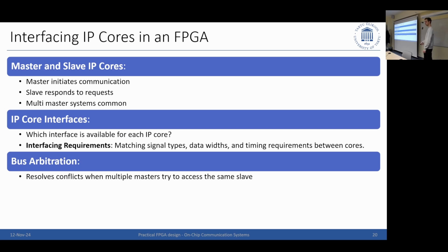Maybe you decide because of this that you want to use AMBA 2 or AMBA 3 on the overall system, so use AHB. And of course that's a valid option. But you also see that I can do everything else with AXI, so AMBA 4 would be much more efficient. I have only one thing which I have to convert. That's something, again, which you have to look into in the beginning.